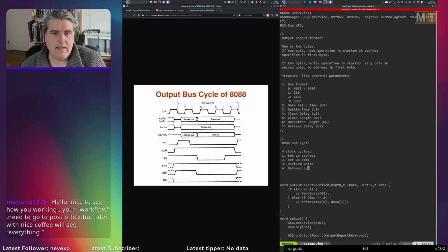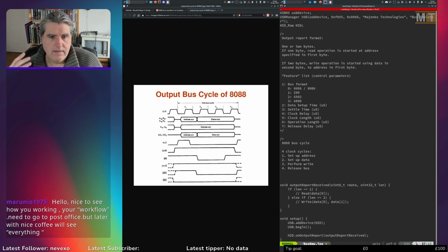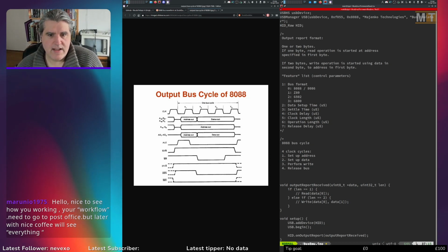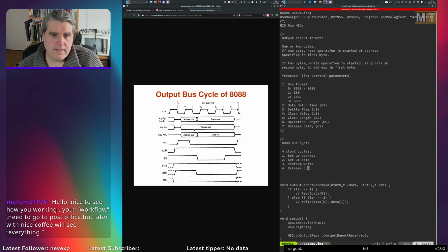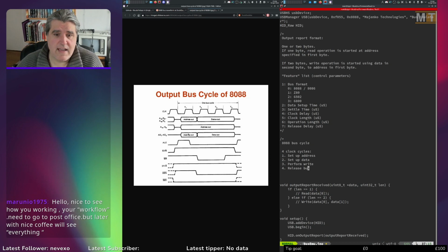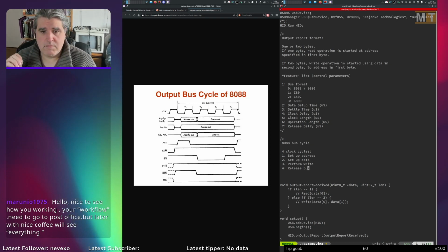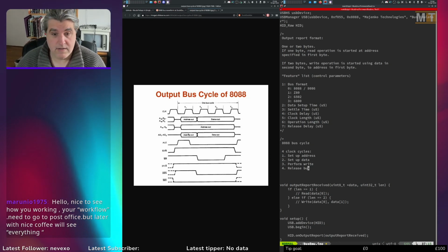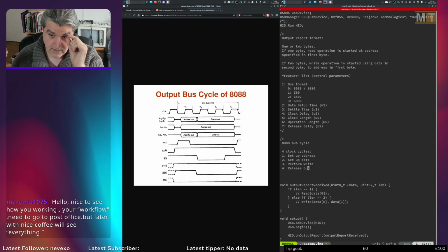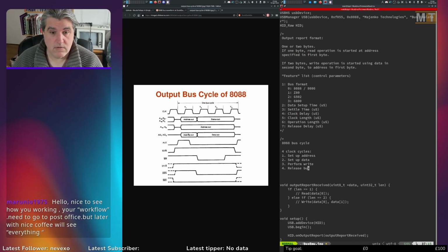So what you see normally is the decoded and latched address from the multiplex. So this section here where it's latching the address through the data pins, I'm never going to actually create. I'm just going to set up the address, next clock cycle, set up the data, next clock cycle, do nothing really while it does the write. Next clock cycle, release all the bus.